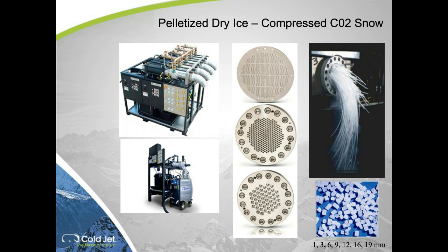That liquid that was reclaimed from the gas is put into these copper tubes at the top of the pelletizer, the top left picture. Liquid goes in there, goes into that cylinder. That cylinder is a discontinuous process, but when it is stroking forward, it looks a lot like strand die extrusion, like a pasta maker. That liquid will flash into a snow at ambient pressure. That snow is then pressed through a die, and you make whatever size pellet or nugget that you want to make.